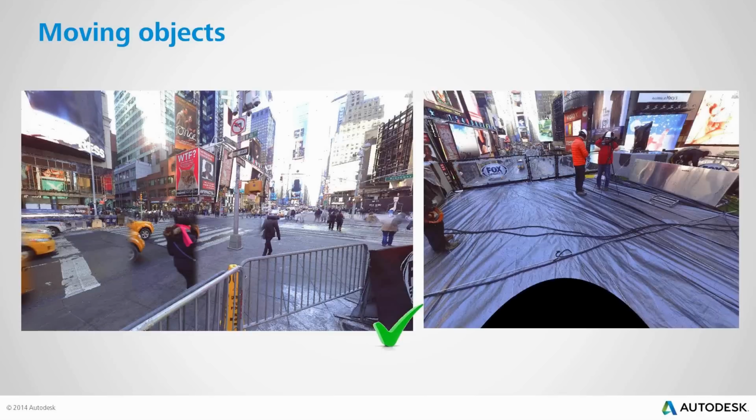This was a temporary structure that was actually being built in the middle of Times Square, and there were some scans collected on the roof of that temporary structure. And the roof was covered in this black tarp. And as people moved around on the roof and as equipment was moved, cables were moved, even the wind blowing, this surface was changing significantly, a couple of centimeters depending on where you were. So it was a very fluid type of surface that was being scanned.